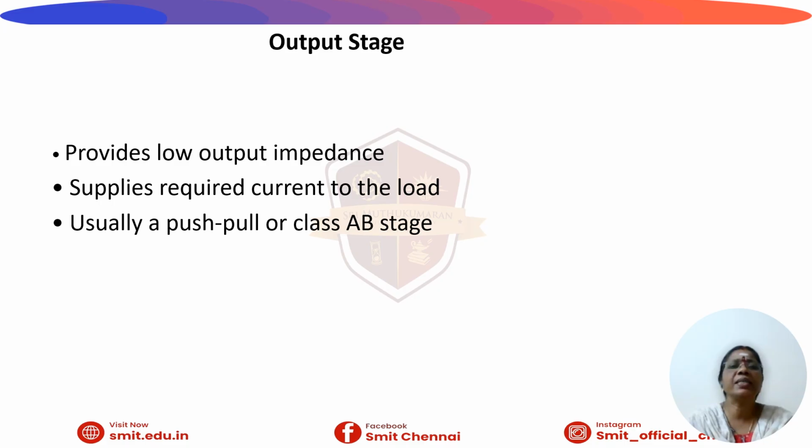The final stage is the output stage, which provides the low output impedance. It supplies the required current to the load. Successive to the output stage, it is usually designed using a push-pull or class AB stage, and the output is the amplified output of the input signal.